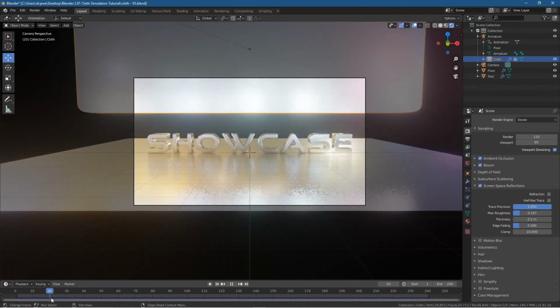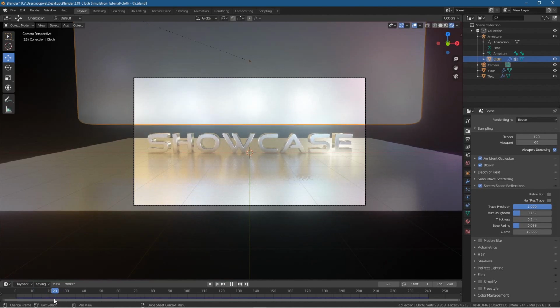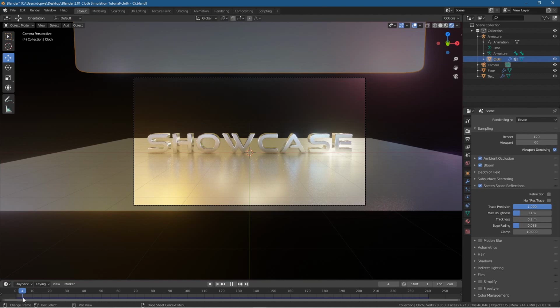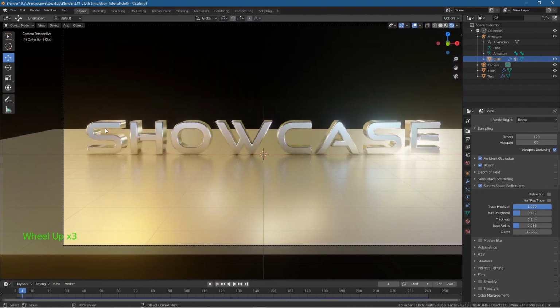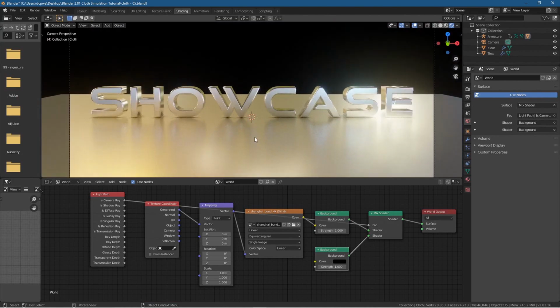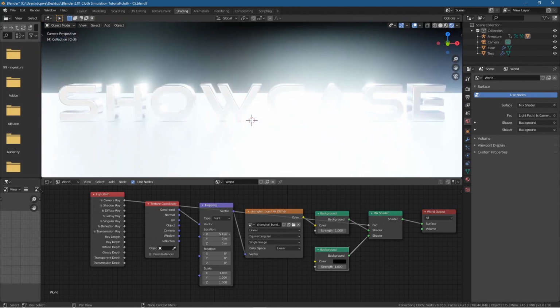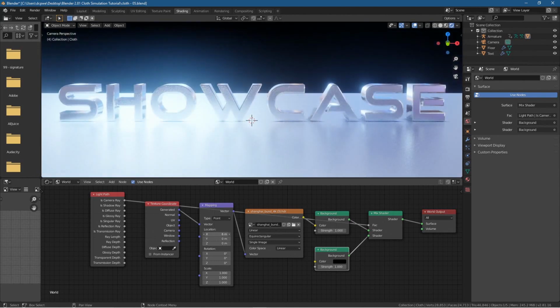One thing we can do is, let's just see, let's bring that material above the camera. Let's move in towards this text here. Let's go back to our shading, zoom in on this text here, use the mouse wheel, and here in the X location we can rotate around to change the colors. So we want to change it to maybe like this nice shade of blue.